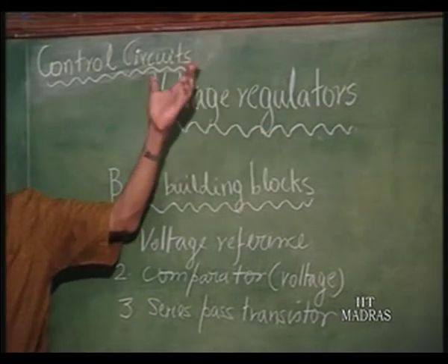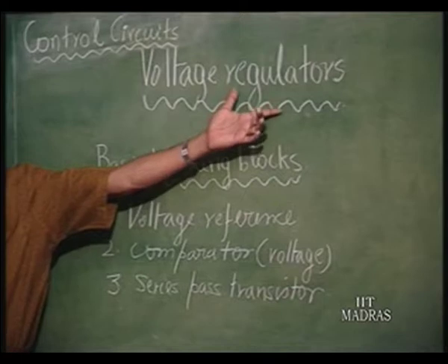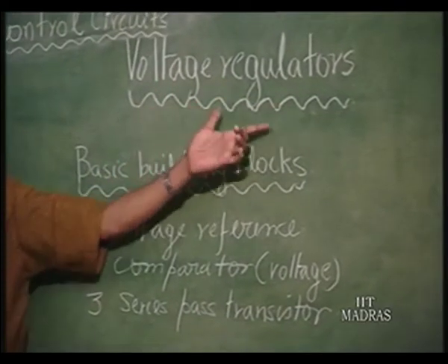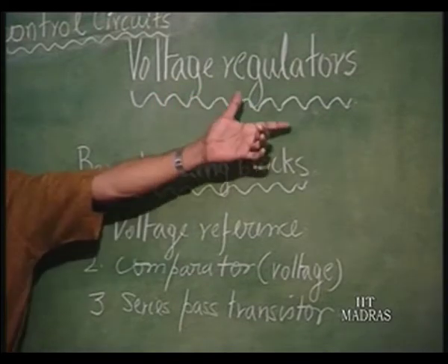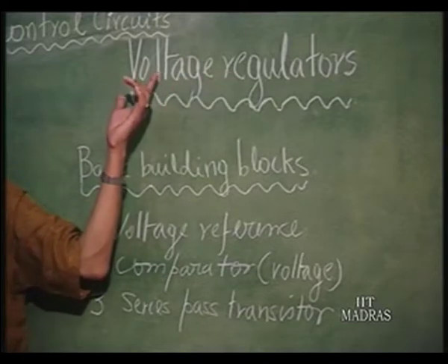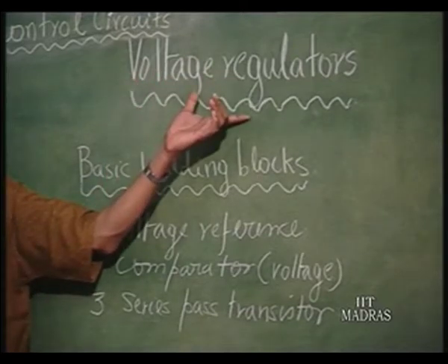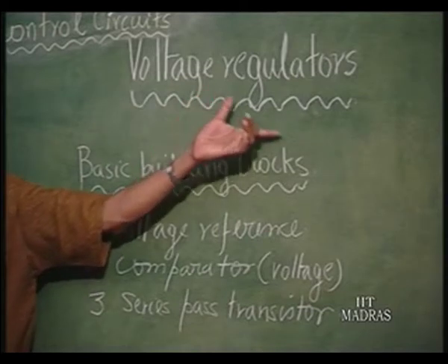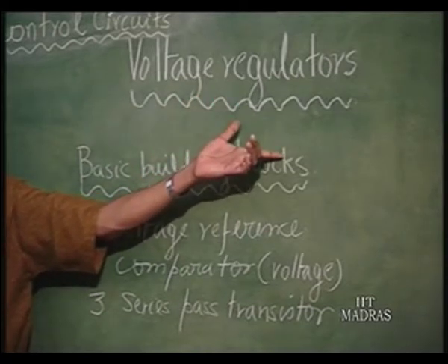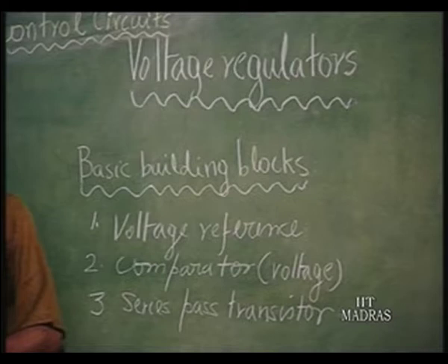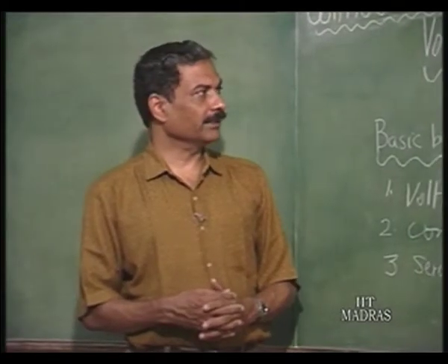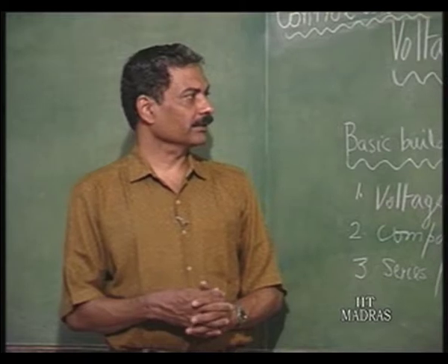It may be a DC voltage regulator. We can have AC voltage regulation, which we will call automatic gain control system or automatic volume control system. So, when we say voltage regulator, normally we mean DC. We can also build AC voltage regulators in our electronic system, that is amplitude stabilization of oscillators. Then, let us say AGC systems, AVC systems, these are all AC voltage regulators.